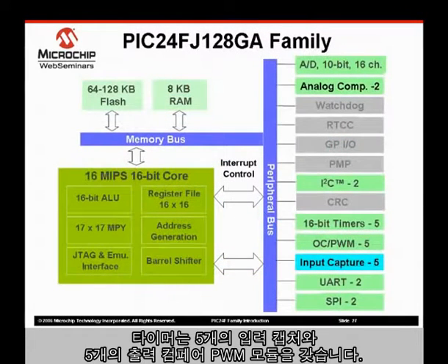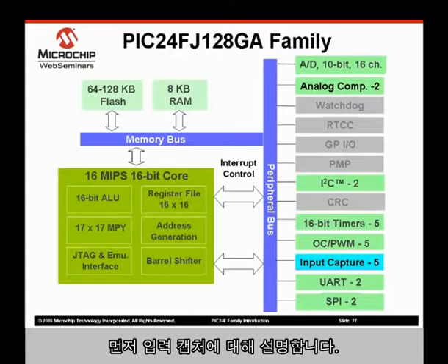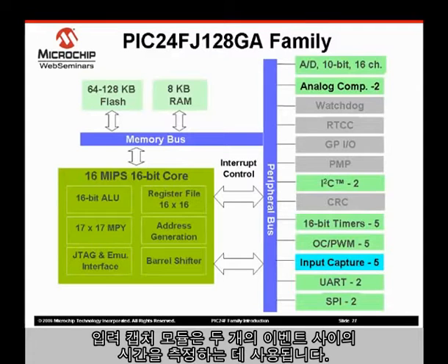Coupled with timers are 5 input capture and 5 output compare PWM modules. First, we'll take a moment to discuss the input captures. Input capture modules are used to measure the time between two events.